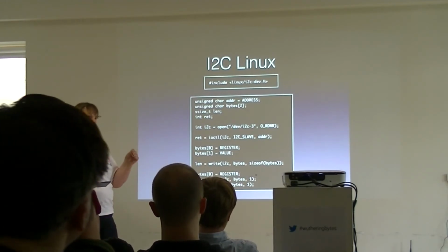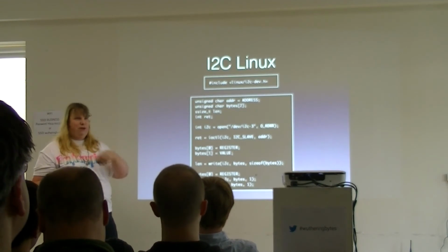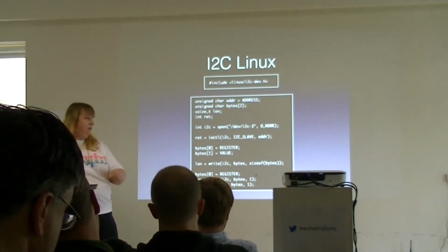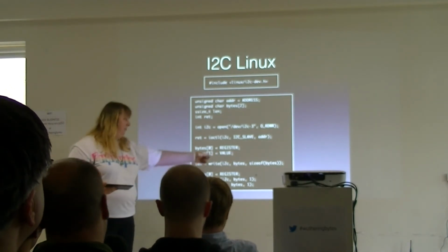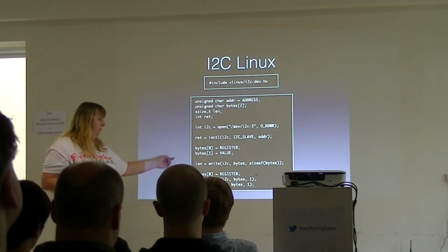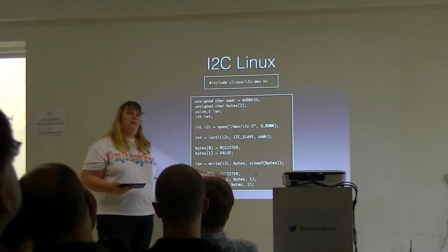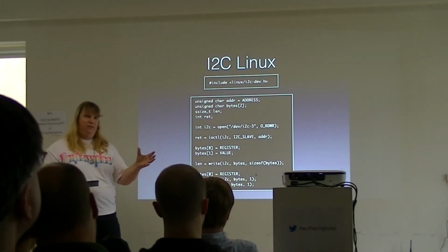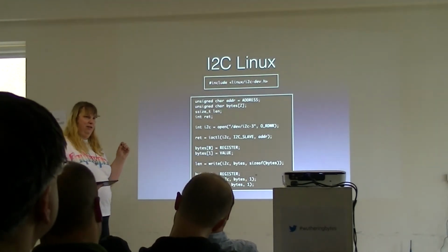So you'll need to say which register you want to write to or read from before you actually send the value. In our one, we've got a byte value that we're sending to some register. If we want to read from it, we have to write the register value we want to read from out, and then we read back the value for that register.